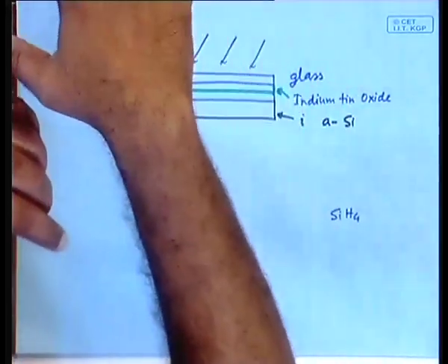While it does so, silicon will have a lot of dangling bonds. Then some of these dangling bonds are satisfied by that excess hydrogen, which is again separated out, that is also in that environment. That hydrogen sort of satisfies some of the dangling bonds, as a result forms what is known as not exactly silicon, but silicon hydrogen alloy kind of thing.